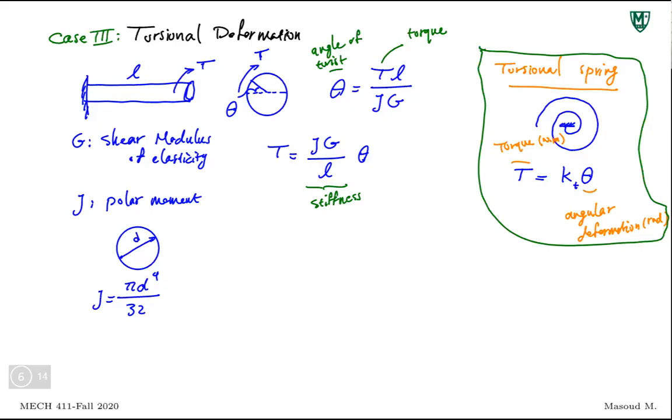So as long as you know the polar moment and you know the shear modulus of elasticity, you're good to go. You can model this as a spring mass system, or as a spring. You can model the shaft as a spring.